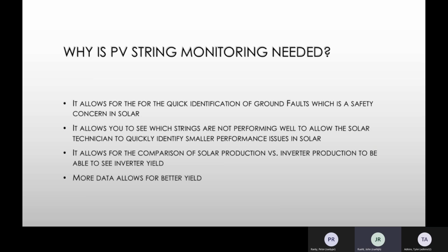Why is PV monitoring important? It allows for quick detection of ground faults for technician safety. It also allows for more data to be collected to allow for quick identification of performance issues with inverters or the array itself, which leads to higher power yields.